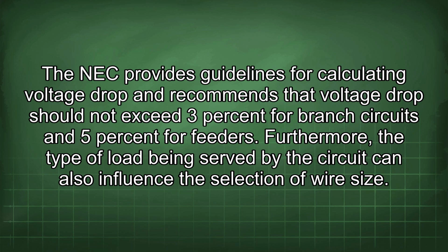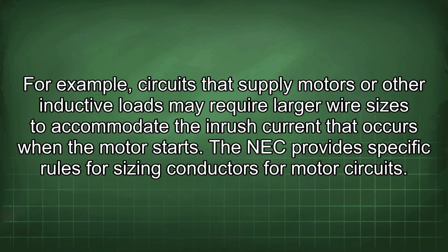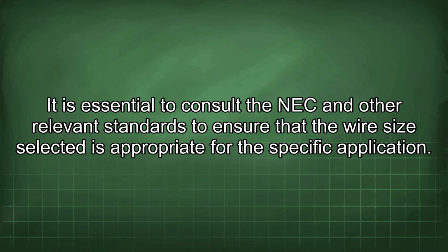Furthermore, the type of load being served by the circuit can also influence the selection of wire size. For example, circuits that supply motors or other inductive loads may require larger wire sizes to accommodate the inrush current that occurs when the motor starts. The NEC provides specific rules for sizing conductors for motor circuits. It is essential to consult the NEC and other relevant standards to ensure that the wire size selected is appropriate for the specific application.